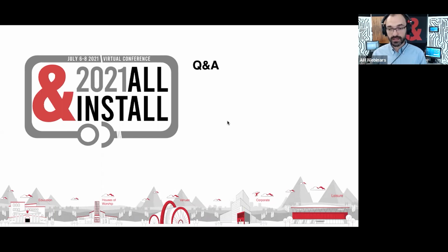Again, we tested that setup to see how the combined AC would work in terms of the AHM64 on one side and Teams on top of that. And we found that actually there's no conflict whatsoever, because what happens is the hardware AC is first in the chain, in the signal path, and will essentially remove most of the echo or all of the echo in the best situation. And the Teams algorithm will then essentially pick up a cleaner signal without any echo, and that's absolutely fine. So no conflict, and you can go ahead and use it with any of these apps without any problem.